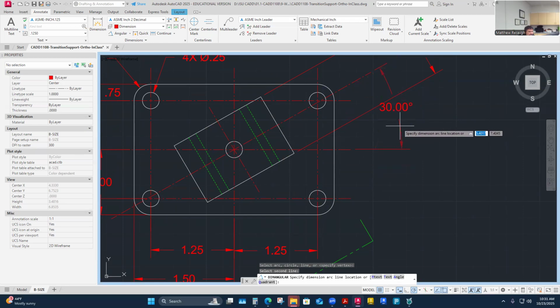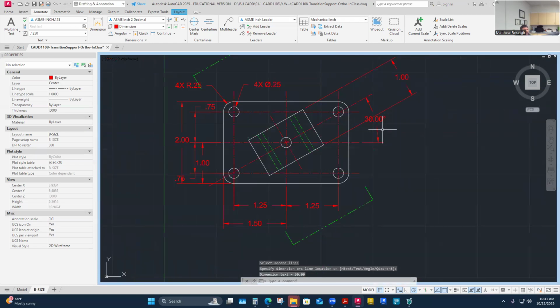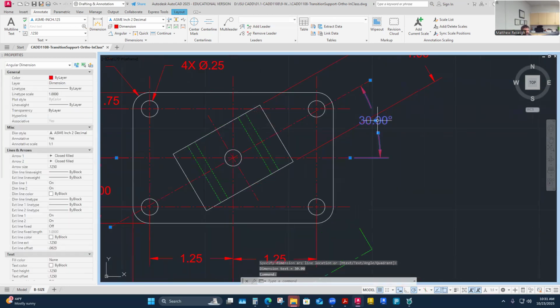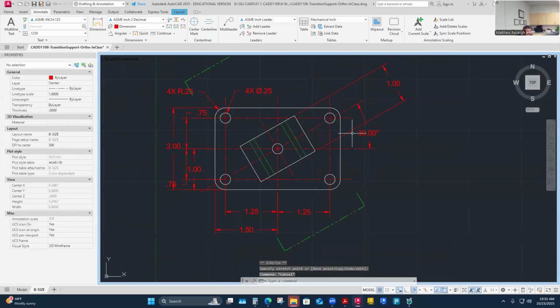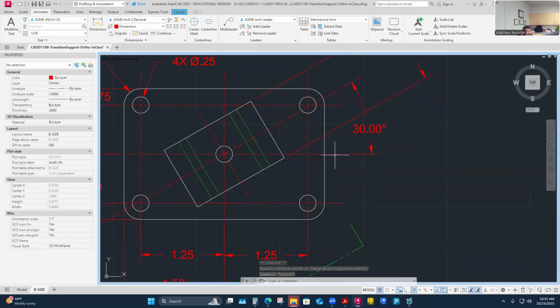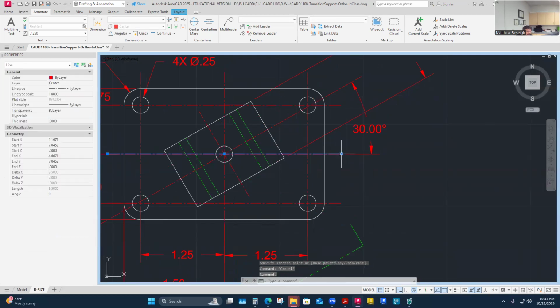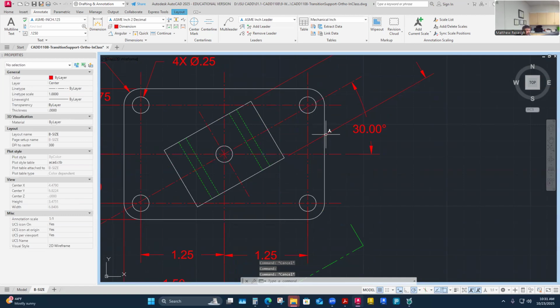It was critical for us to draw it, and where I'm going to put that in, I don't know. I'm going to put it in off the part, and I might have to move it a little bit here once it's there, so I don't get that dimension line interference. I'm going to have to cut that extension line eventually. So this is off a nice controlled center line, and it's 30 degrees tipped. And I wouldn't put parentheses around that. It might be my critical hold. This is 30 degrees. It has to be 30 degrees. Okay.